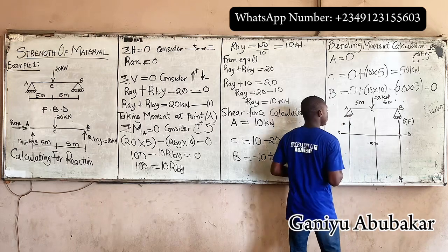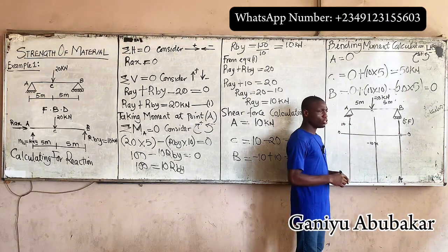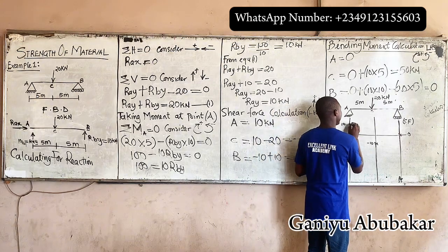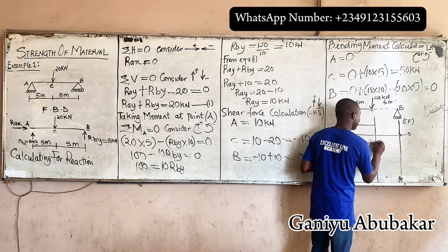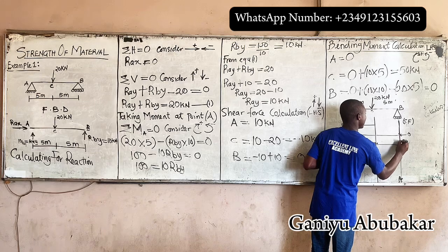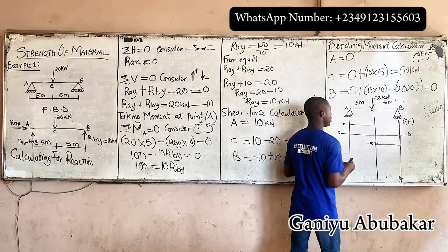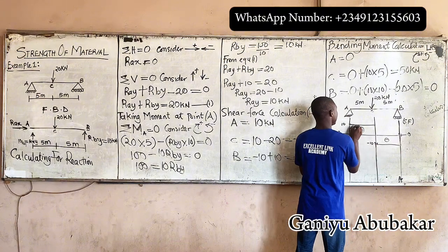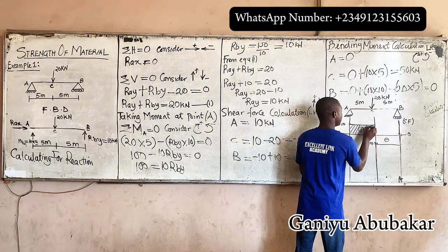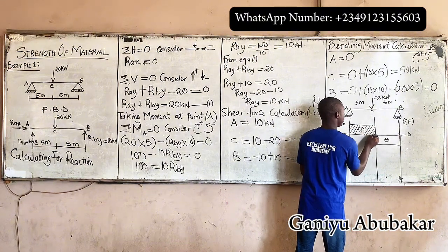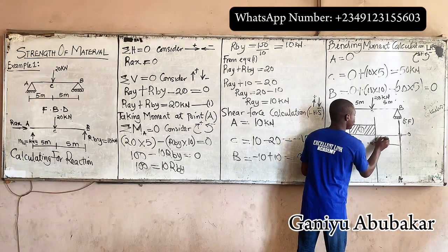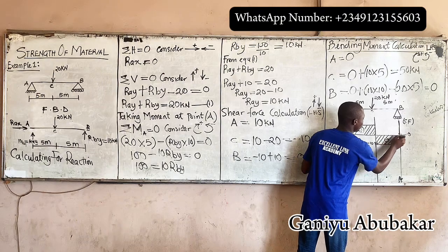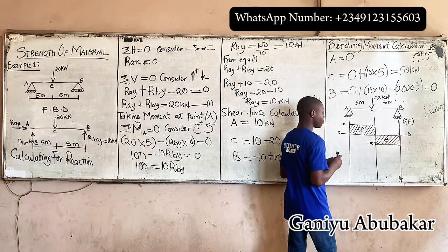So when it comes to your shear force diagram for point load, connect them what? Rectangularly, in a rectangular manner. So this is a positive region and a negative region. So I have something of this nature. So this becomes my shear force diagram for that particular question.